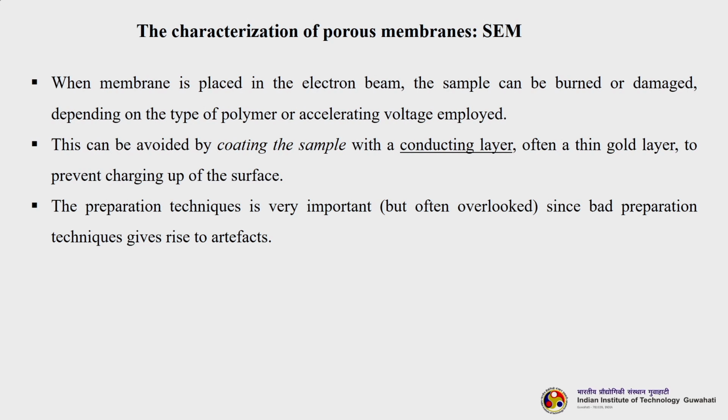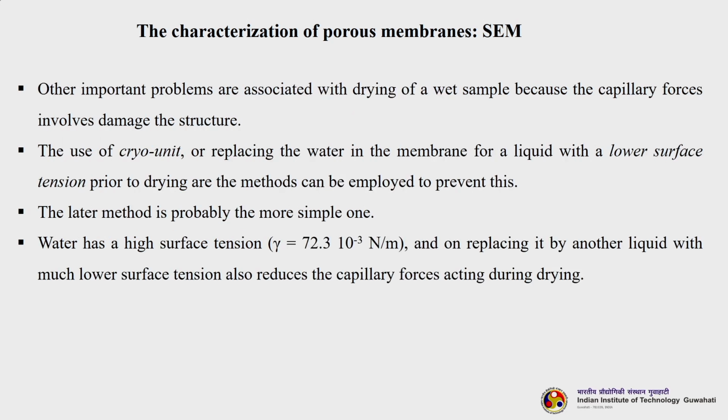This can be avoided by coating the sample with a conducting layer, often a thin gold layer, to prevent charging of the surface. The preparation technique is very important, but many times it is overlooked. Because if the preparation is not good, then you will get a bad image. Another important problem is associated with drying of a wet sample, because the capillary process involves damage of the structure.